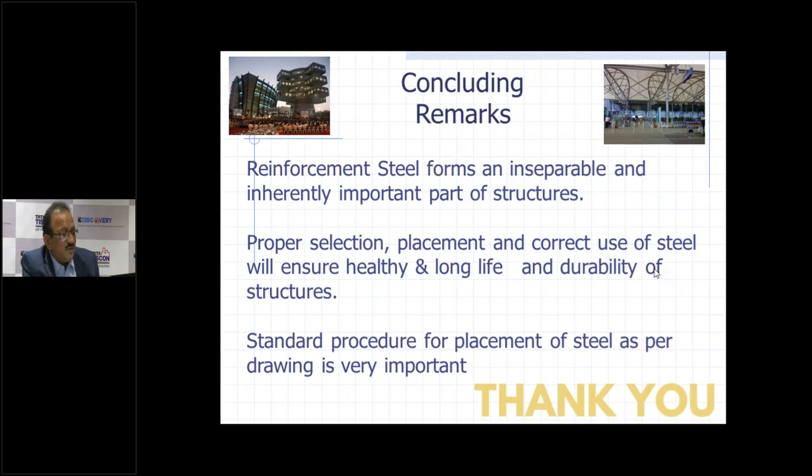How can you avoid corrosion of reinforcement if the procurement is done earlier at the construction site? This is Vadiraj Rao and NR Rao asking this question. We have to protect the steel from corrosion, as I mentioned in how to store it. Number one, cover it with plastic sheets so that the moisture and atmospheric humidity do not cause corrosion. And if some corrosion still happens, then the age-old practice is to put cement water slurry on the steel bars and then use it. But there are also some corrosion-resistant paints available in the market these days, which are very frequently used for high durability.